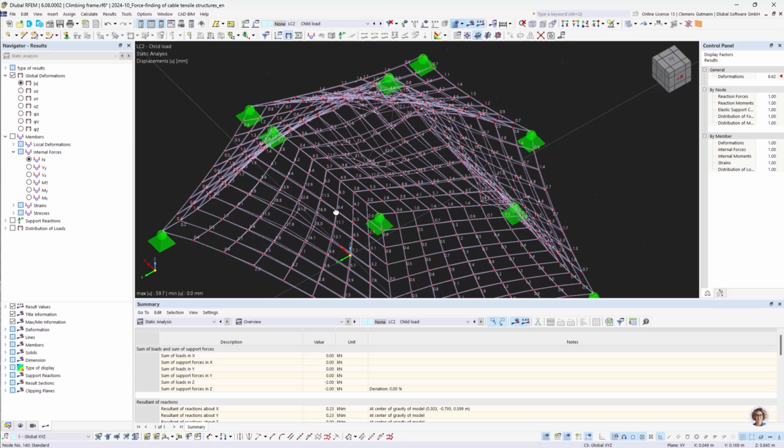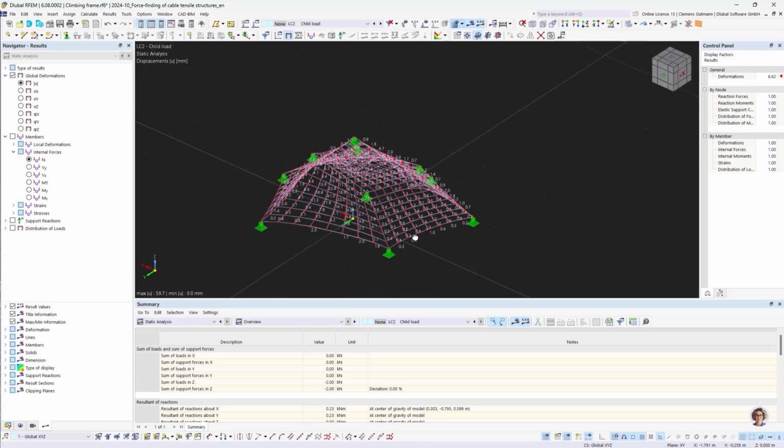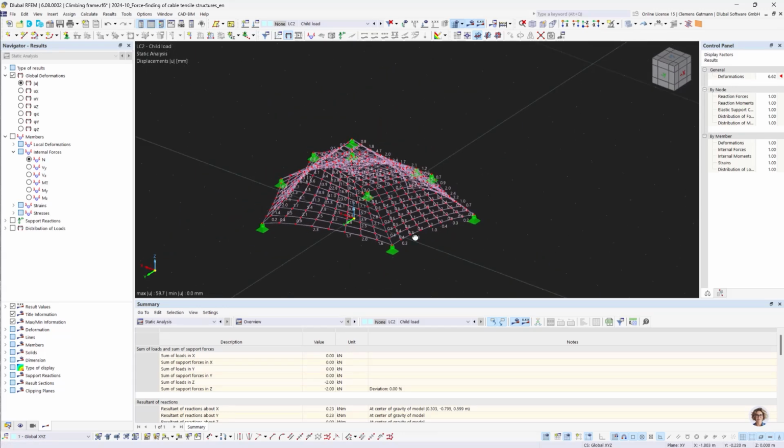Still, I think okay, but of course, there's an influence of the pre-stress level later on, not for the form finding, but if you use the form found and pre-stressed structure for additional loads, it makes a difference what pre-stress level you have applied to the model. And this is all I wanted to show you today. And thanks for watching, and I'll give back to Andreas now.